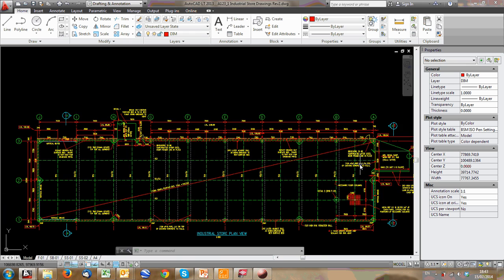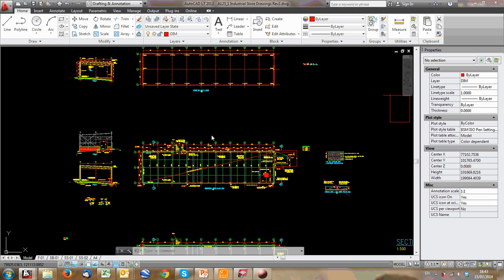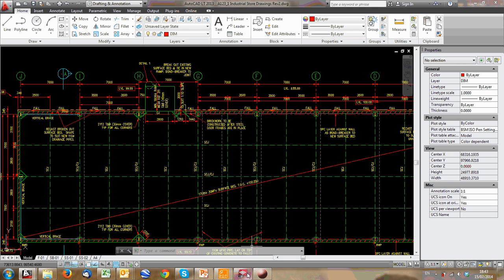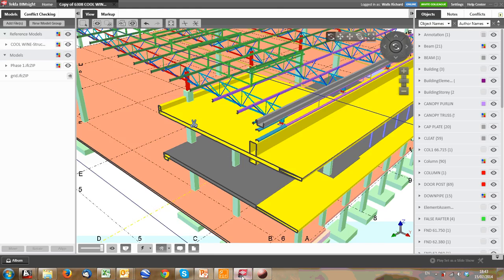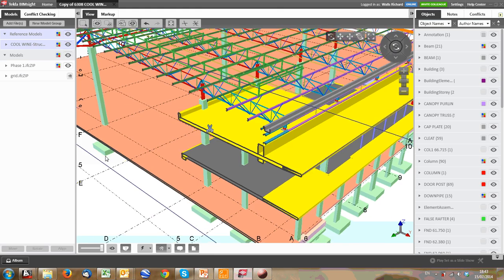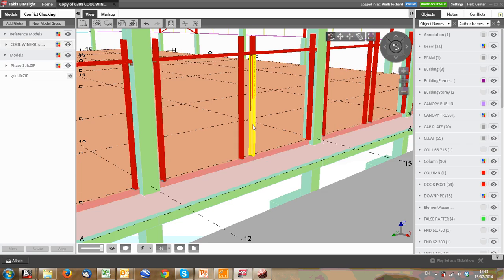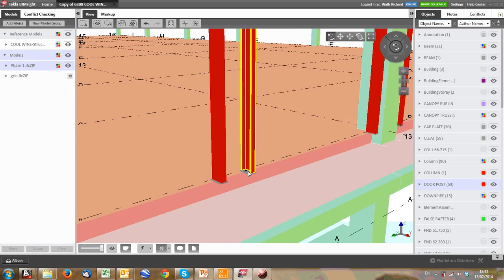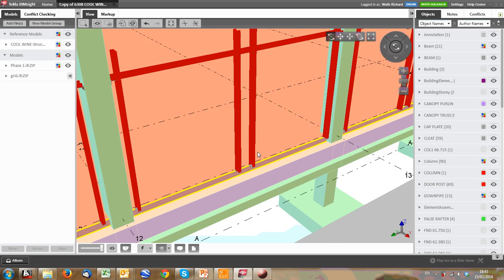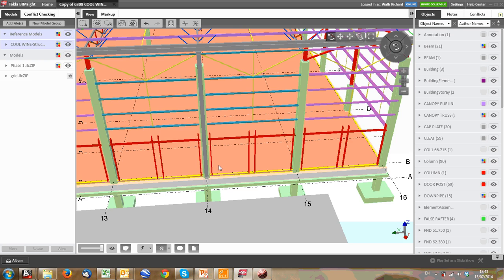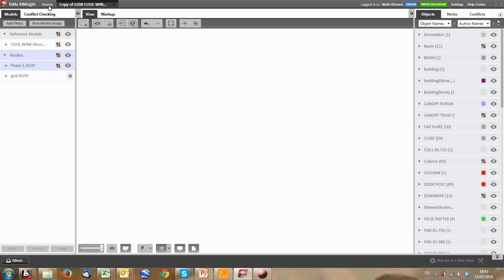Now we've got all our concrete layers and all our steelwork together. We just need to make sure that they fit together. A couple of things that we might need to add to make sure that this interface is right. I'm going to actually show you here. You need to make sure you've got posts for your roller shutter doors. These are posts. These are just open channels, actually quite lightweight, 3mm thick open channels. The detail works quite well. Normally, otherwise, you use cold formed lip channels.